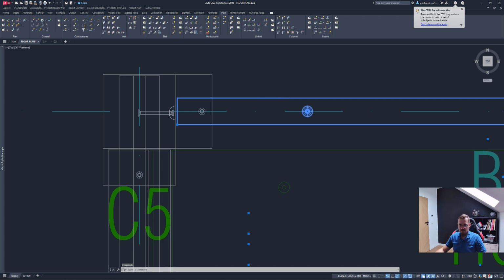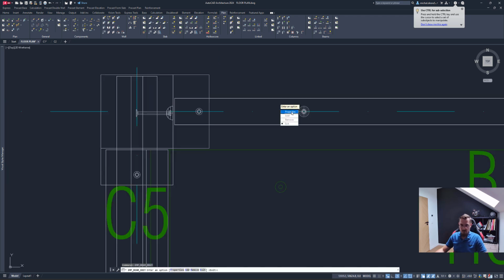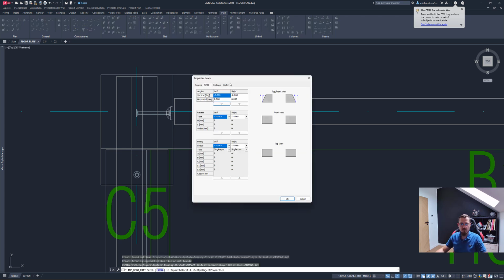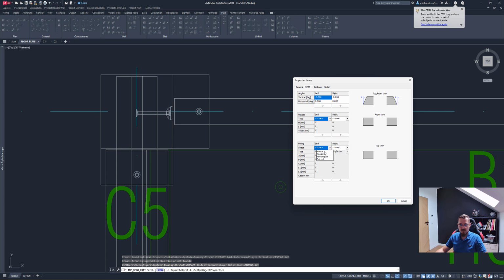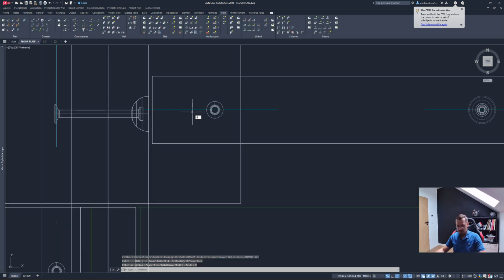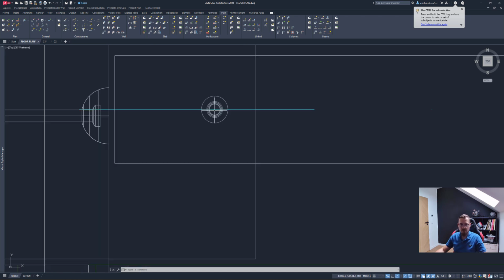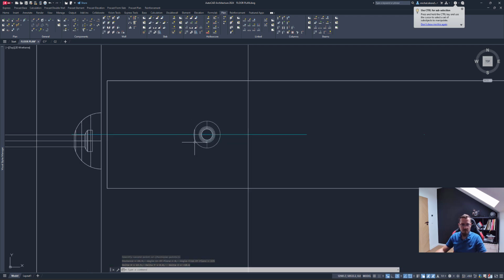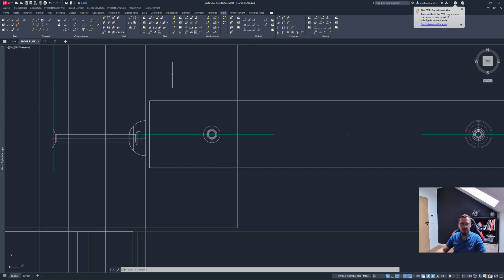Easy, really. Let me select that. This is B2, so once I edit this, all will be edited as well. I need to go to ends, and I will need to create a circular opening at the end, and it's a matter of specifying the diameter. So let me measure first, so it will be easier. Dimension, let's measure that. So 170 mil from the edge to the center of the opening. And I also want to know the diameter that I want to have, 22.5. So 55 millimeter opening should be good.